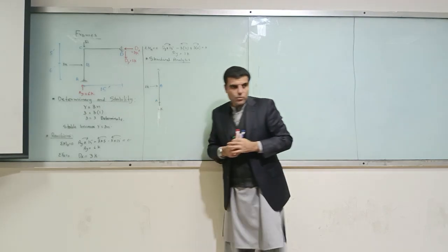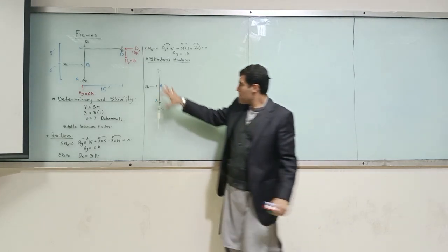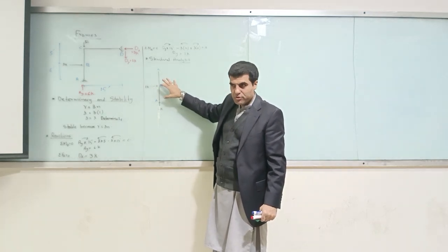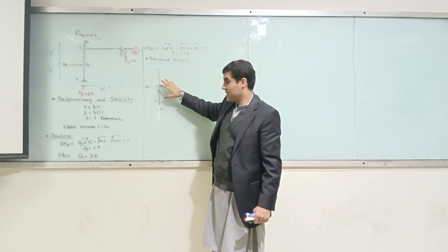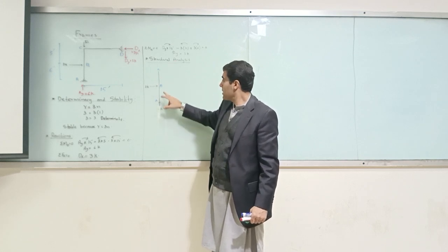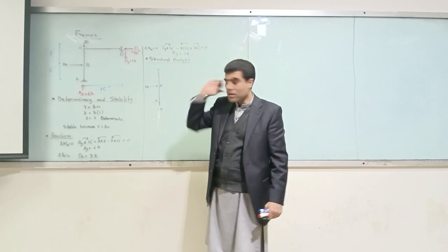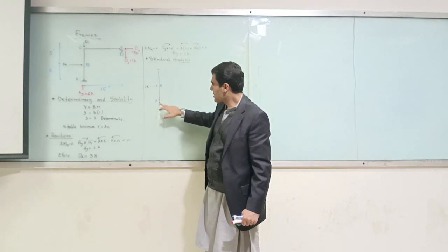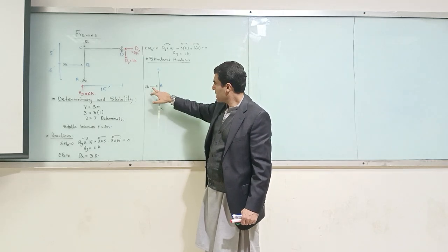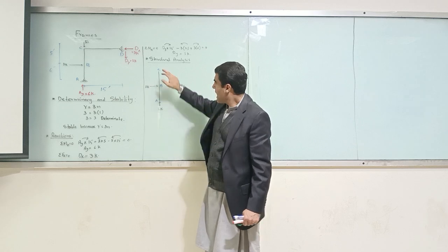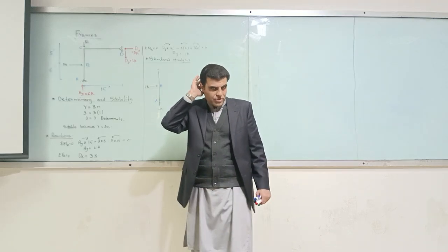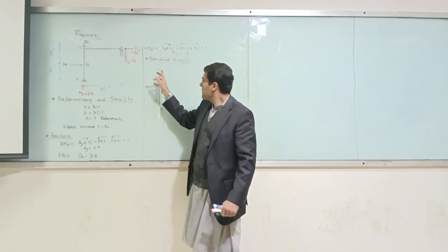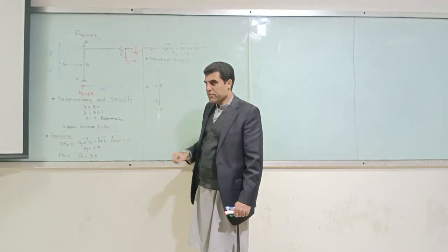Okay, now we do structure analysis. By structure analysis I mean we find the body forces and then the internal forces and shear force and bending moment diagram. So we have got AC member. AC member has got force 6 kip. It has got 3 kip over here applied. Every point on the structure must be in equilibrium, so every point must satisfy the equilibrium equations.